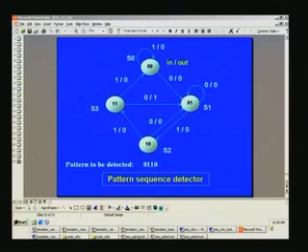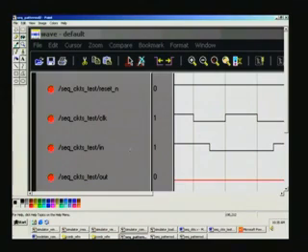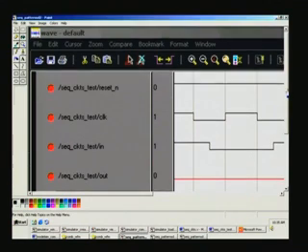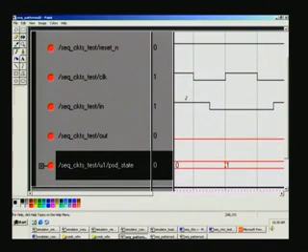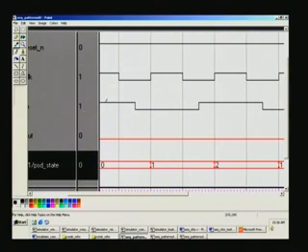Now next we have the second set coming over here, and you can see that from state 0 we are moving on to state 1. Let us see what happened in the meanwhile. First, the input is now 0. Earlier it was 1. The very first pattern coming is 0 here, and at every clock transition it is being reckoned.